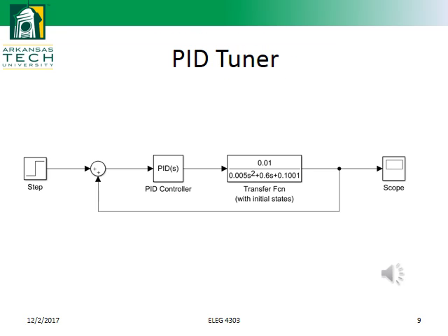To analyze the motor's transfer function using a PID controller, the PID function in MATLAB was used. The DC motor transfer function was input as a transfer function. And then within the PID controller, there's a capability to tune the PID inputs to match what we were looking for as far as our rise time and our percent overshoot as the outputs from the transfer function of the DC motor.